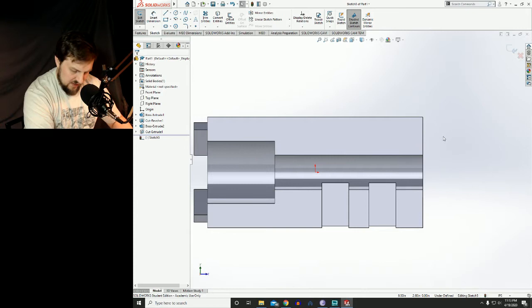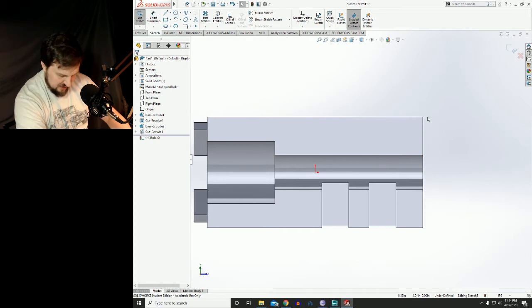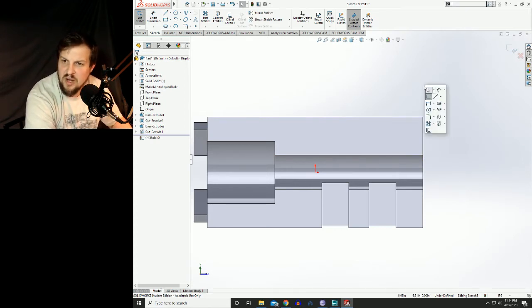So next up, let's go ahead and create our shape. So our shape here is going to be a rectangle with a circular edge on it. So I'm going to do this a little bit different than the book. The book doesn't really go through how we're going to sketch this. I am. So first, what I would do in this case, I'm going to go ahead and hit my S key. I'm going to go ahead and get my 2-point corner rectangle.